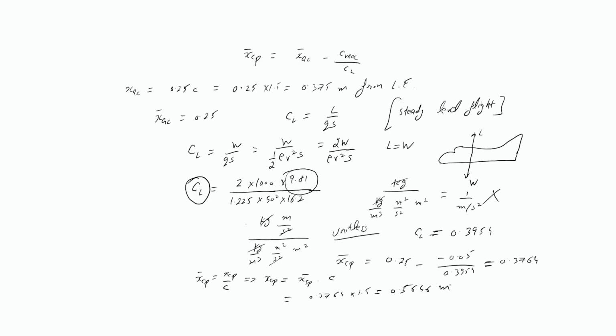So let me write here what exactly this means. This means that the CP is around 56 centimeters from the leading edge, which is aft of the aerodynamic center.